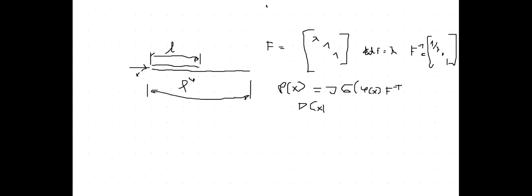So if I have the second Piola-Kirchhoff law, S is equal to E, which is Young's modulus, times 1/2 (lambda squared minus 1). This is your Green-Lagrange strain in terms of these stretches. So P is equal to F times S. Here, this single component becomes lambda times S. So that becomes equal to E times 1/2 lambda times (lambda squared minus 1).